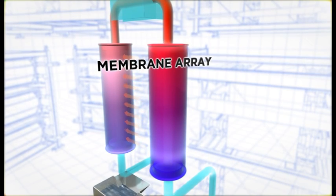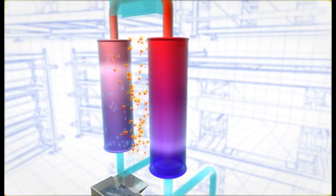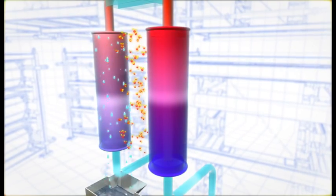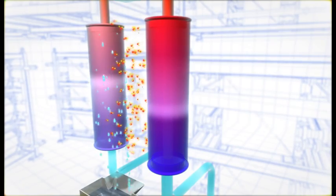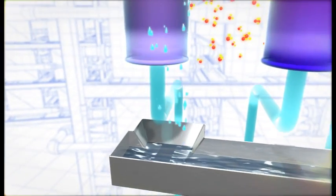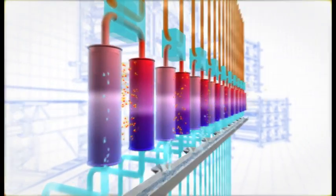Within the membrane array, pure water vapor evaporated from the hot seawater passes through the microporous membrane while the rest of the seawater is retained. Following the thermal gradient, the evaporated water from the membrane array travels towards and condenses on the surface of the condenser array. The retained seawater flows down the membrane array and simultaneously releases heat to the condenser array, allowing efficient internal recovery of evaporation heat.